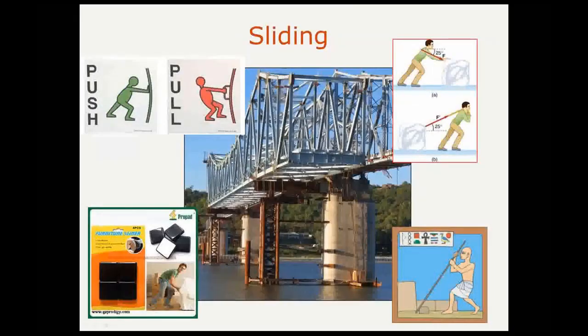So when we designed these piers, we had to consider the effects of that construction sequence. So we had all the usual forces on the pier. We had wind, we had traffic loads from the bridge, braking force. We also had barge impact to consider, but on top of that, we had to think about, is this bridge slide going to create forces that we need to design into the piers?